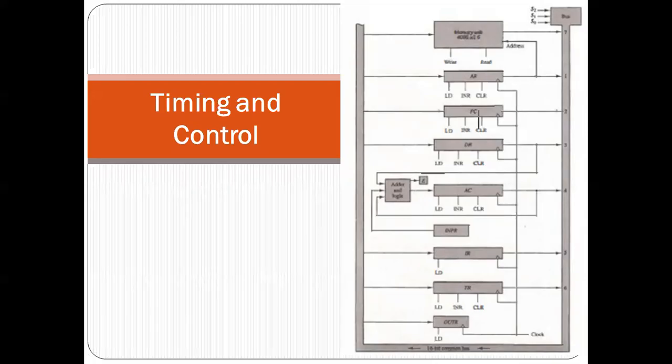The memory reference address should be held in AR. The first step of the fetch is getting the 16-bit instruction code into IR. The instruction register should hold those 16 bits. That is what fetch is, right?